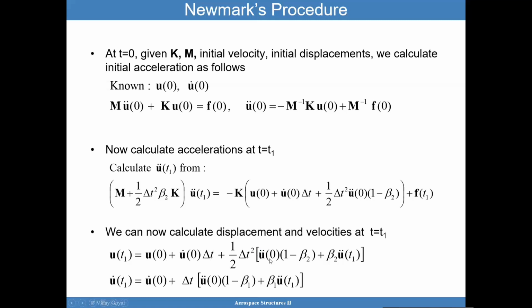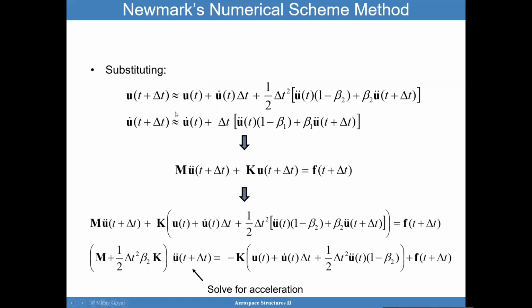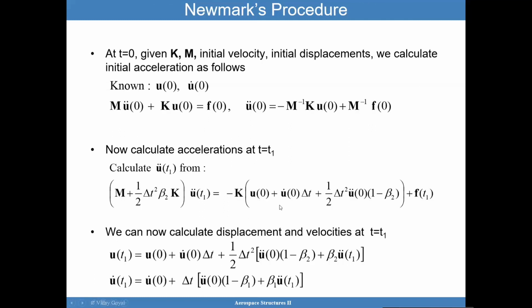So I'm using the equation we had here at the top, which is your Taylor series expansion, but the glorified version. The accelerations are known from this step, and I know the accelerations from this step here. So this is all known. Now I have marched the solution forward, and I know the deflections at time equals t1.